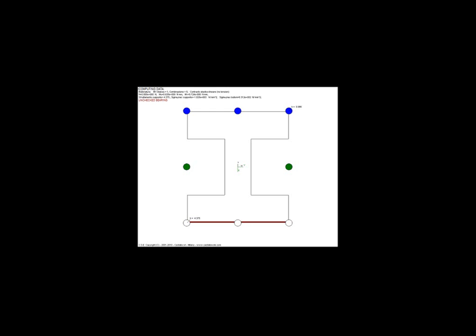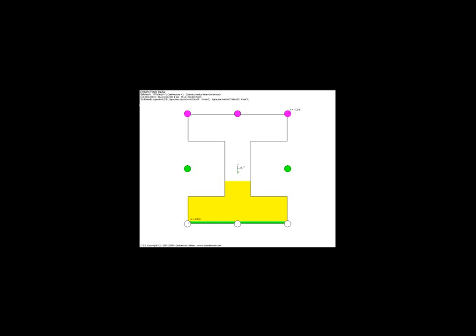Now let's set m equal to 10, considering the elastic modulus of the bearing support to be 1/10 that of the bolts. The resulting distribution is as shown. The part of the bearing surface under compression is larger. The peak stress is lower, 0.210, and the normal stress level of the tension bars is much greater, because the arm of the internal couple is now smaller.